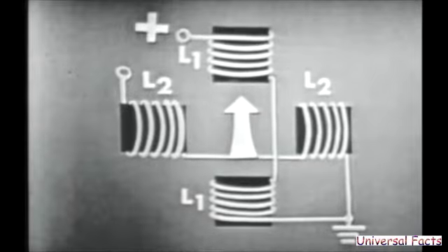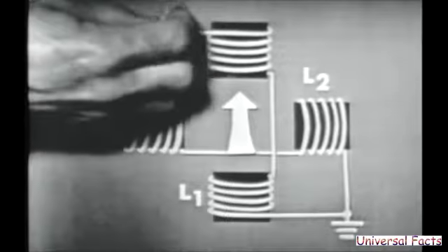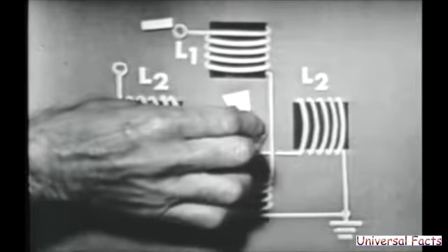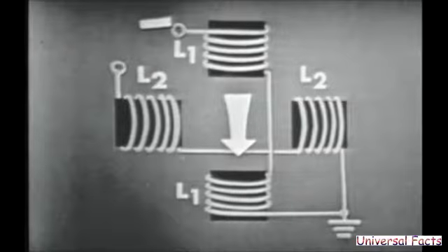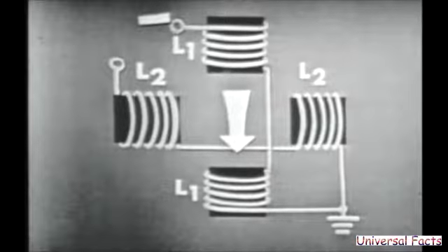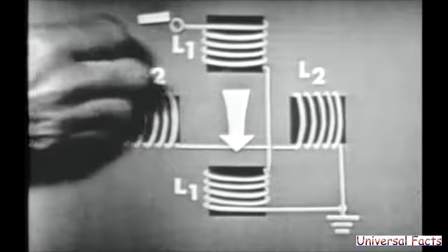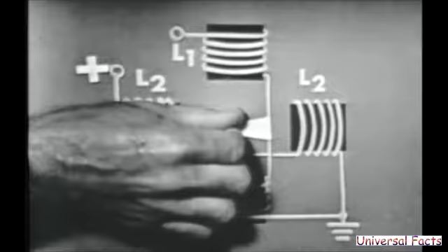Another good point is, if we reverse the polarity on L1... Make this a negative, in other words. Right. We'll, of course, reverse the direction of the magnetic field produced by L1. And the rotating magnet will again line up with this magnetic field. Now, the same thing, of course, applies to L2. With voltage applied only to L2, we'll produce a horizontal magnetic field. Like that.